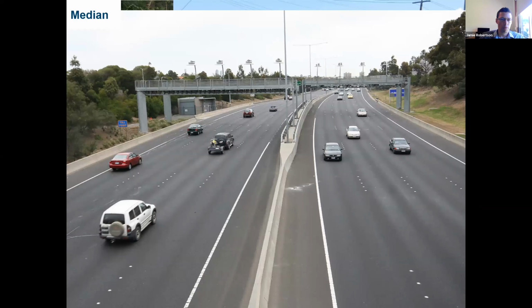In an urban or high-speed, high-volume environment such as this, concrete is typically the go-to because we have a high proportion or a high number of heavy vehicles, and we must prevent those vehicles from penetrating the barrier and ending up on the wrong side of the road. We might also have some critical infrastructure, such as the gantries that you can see there, that need protecting. Given the volumes and the importance of these routes, if a less rigid system was provided, it would likely be impacted regularly. The maintenance burden that would create is also a consideration.